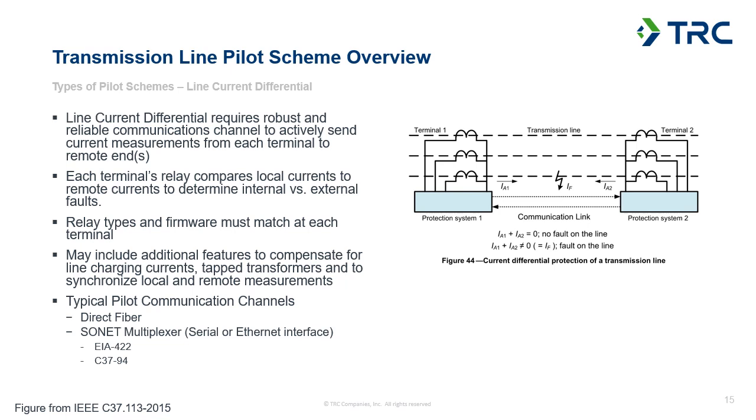So that's one of the reasons differential protection is popular when we're able to apply it. The difference between our normal operating measurement for our operate quantity, which in this case is normally around zero, and what we have for a fault is very different. We're going to go from seeing basically no differential current up to seeing a very high magnitude of differential current. So we can make a very secure trip decision based on those measurements, assuming we don't have other major sources of error.